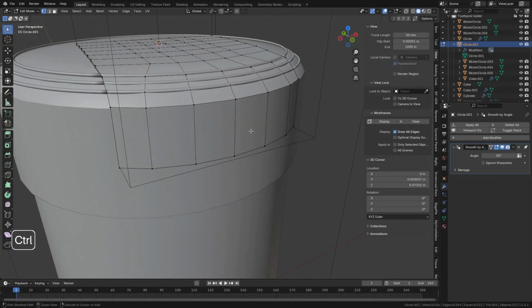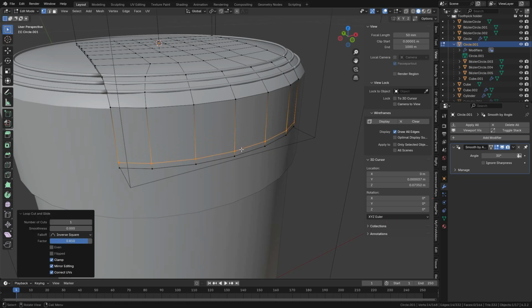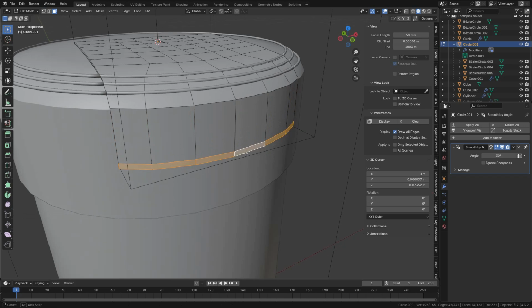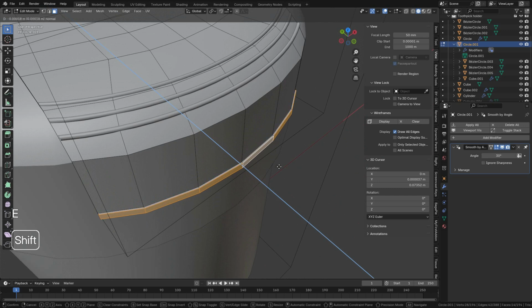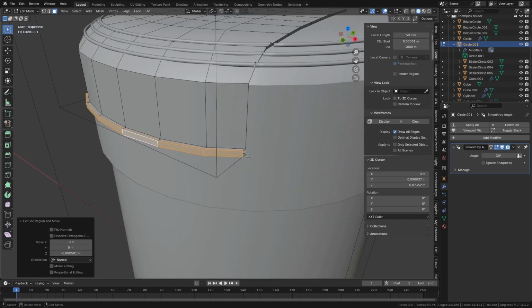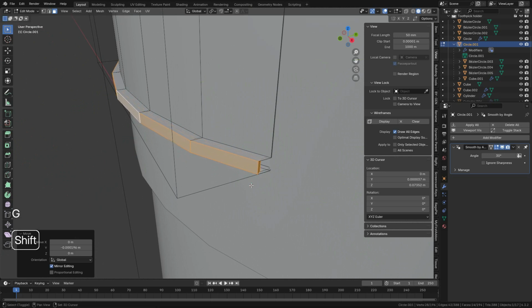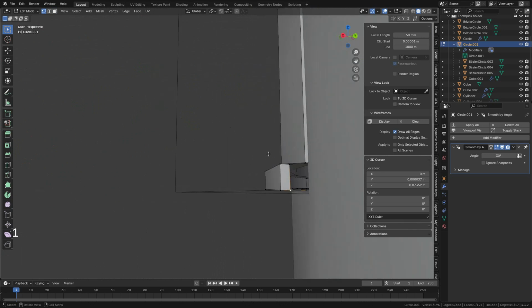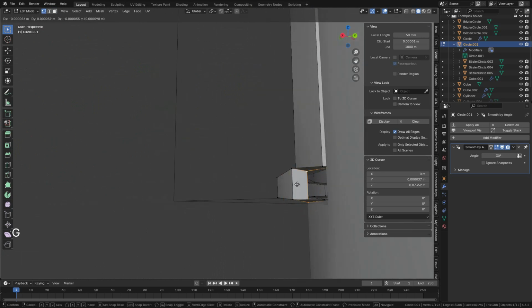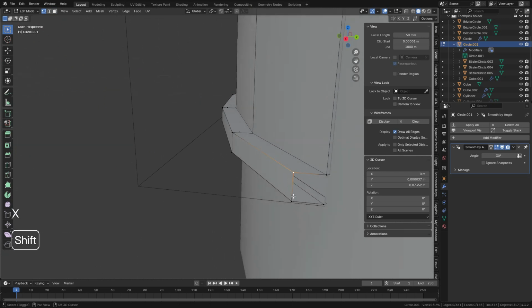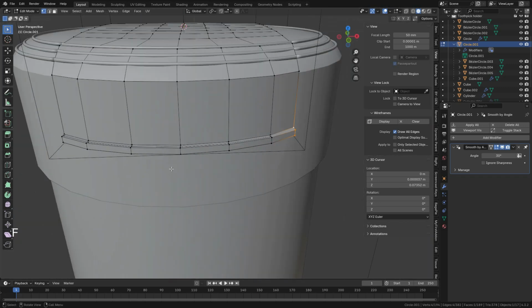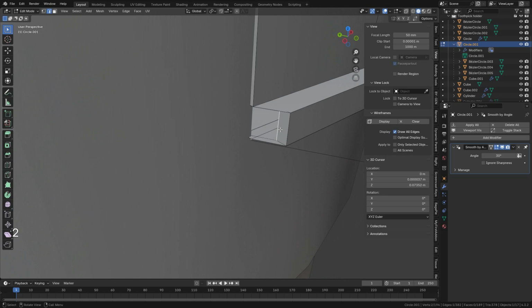Okay, so to create that hinge, or that little nudge or handle, we press Ctrl R, left click, bring them down here, left click again, go to face select mode, press E, and make sure they are brought out just a tad. Bring them out here, something like this. You select these two vertices here, they look like abnormalities, so X vertices. Select these four vertices here and press F to fill. Do the same on this side: X vertices, select these vertices and F.